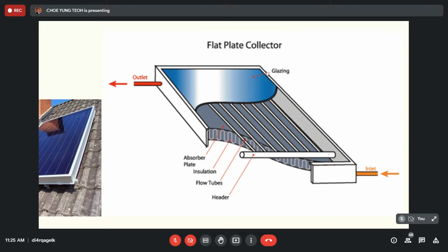And the same thing, if you put the glass under the sunlight for 1 hour and touch it, you feel that the glass is actually hot. So when the glass is hot, it means that other than reflecting the energy, it also absorbs heat energy. So we know that when sunlight hits an object, part of it will be reflected, part of it will be absorbed, and part of it will be transmitted through the glass. So the transmission of the glass will be lower if you put in the glazing, because some of the energy has been reflected and some absorbed by the glass.